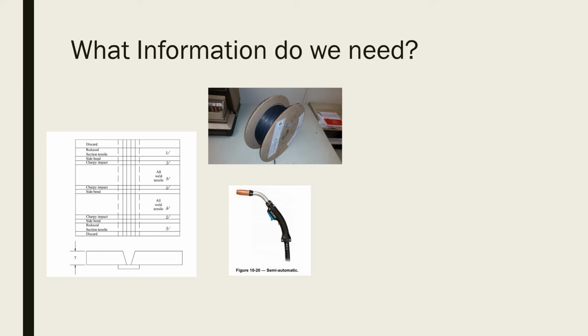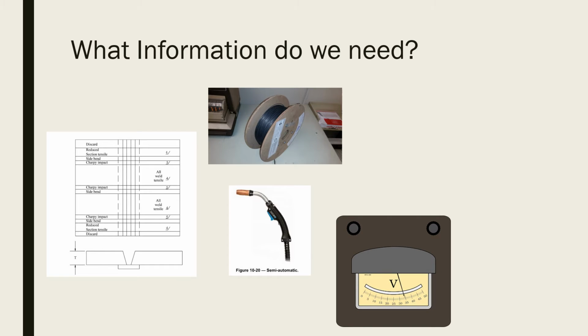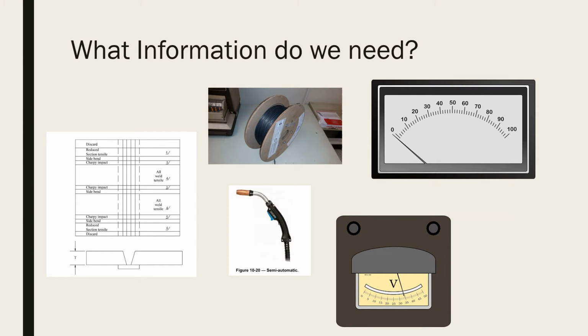Are you welding this up with stick welding or TIG or flux core? What do we got going on here? We're going to give them some parameters like voltage and amperage. We're going to give them, probably a range. We're not going to let them go hog wild, but we're going to look at the manufacturer's recommendation for the filler material we're going to use, and we're going to provide that information to them and give them a starting